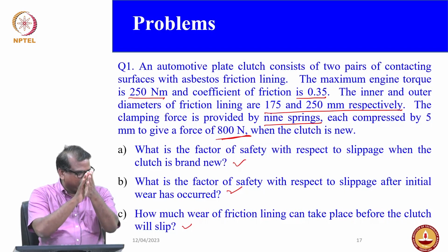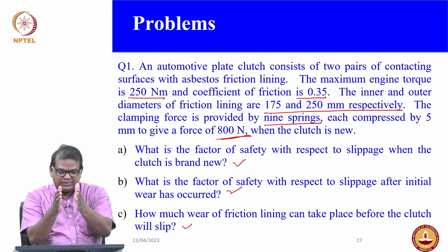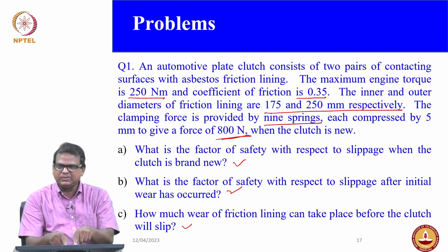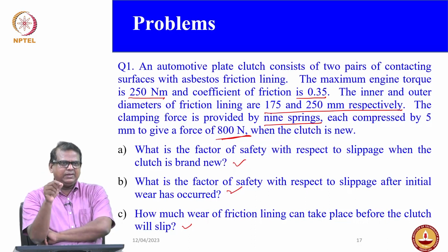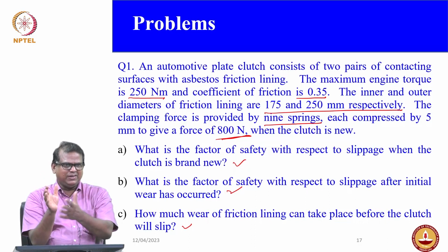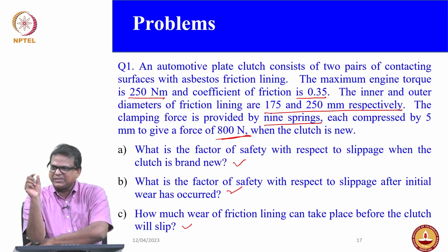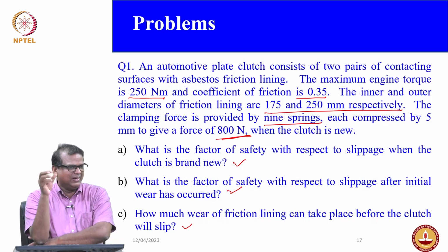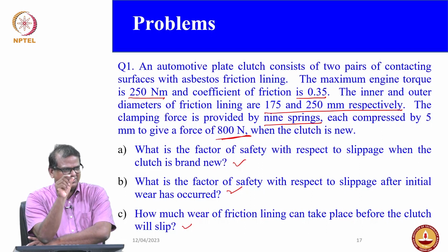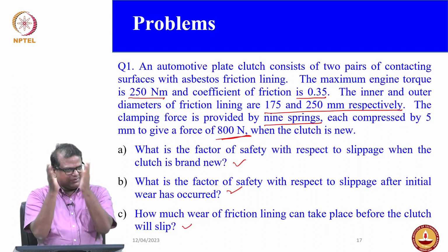No, then you will have slip. So, at what condition are you going to have a slip? That is what is clearly given. So, how much needs to wear out? Yesterday I showed the model also. What is the typical thickness of the friction lining you observed? Is it a few millimeters, 5, 6 or 7, not more than that. So, it is a very small thickness, but of course, it will be there on both sides.